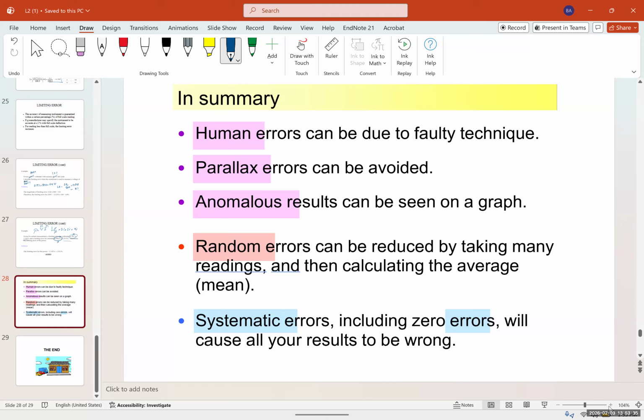So some errors you can mitigate or compensate. For example, if you don't have an accurate system but you have a precise system, you could just shift it, for zero error, drifts, or random errors. But sometimes when you have a systematic error, it's very difficult to compensate for that. But the best way always in errors is to do multiple measurements. That's the reason we usually don't rely on just one measurement. We do it multiple times at different times with different equipment.